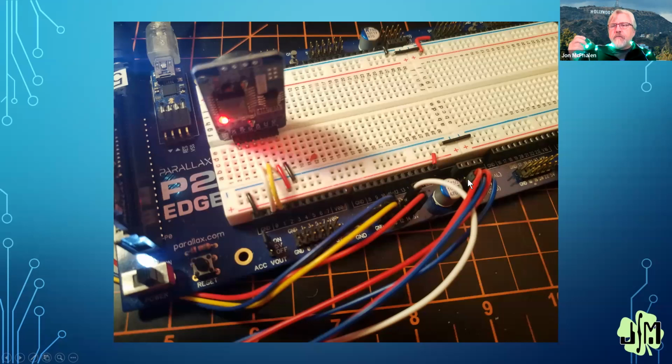Since these can take a bit of current, make sure that when you're running these things, you've got a beefy power supply. I've got a big 5-amp, 5-volt power supply plugged into my JonnyMac, so I can run these as bright as I want without any problems. This is what my board looks like hooked up, and I've tested all the programs we're running today with these connections and verified that it works.